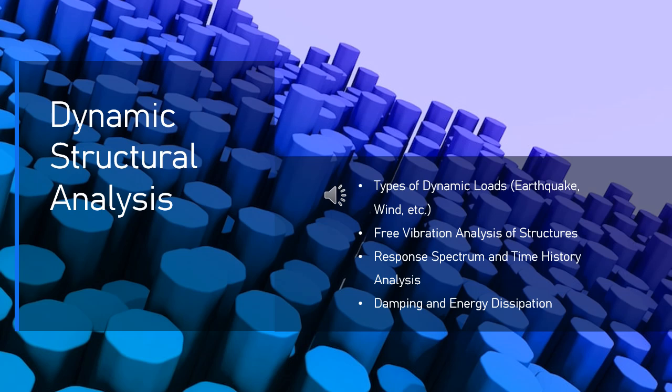Nonlinear capability. Time history analysis can incorporate nonlinear behavior, such as material yielding, geometric nonlinearity, e.g., large deformations, and damping, which are essential for accurately modeling extreme events like earthquakes and large winds. Limitations of time history analysis.